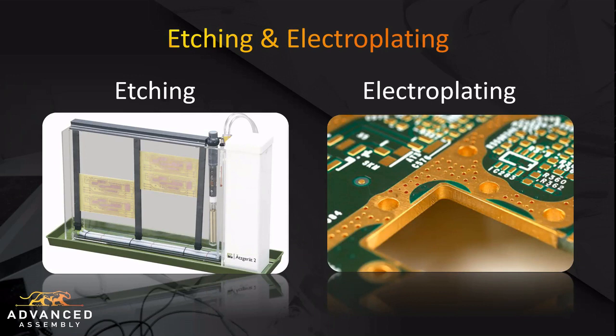Electroplating is used on the external layers of a PCB to add copper. So if your board stack-up requires 2 3/4 ounces of copper, we're going to pull out a thin foil from our stack and then build up the copper on the surface and in the via holes to reach that 2 3/4 ounce per square foot of thickness.